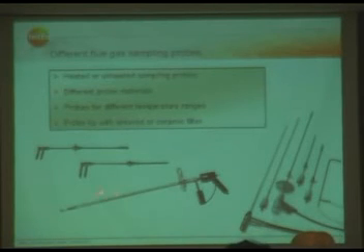That means if you have condensate here within the probe and the flue gas passes through, it could be that NO2 or SO2 gets absorbed. And the result is, at the end, if the flue gas passes the sensors, you won't have any NO2 or SO2 at the sensors anymore, because it got absorbed within the whole sampling system. And this is why you have to make sure that the temperature of your sampling system is above the dew point. In some applications, it's required to have such sampling systems.